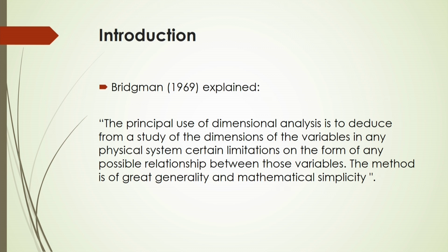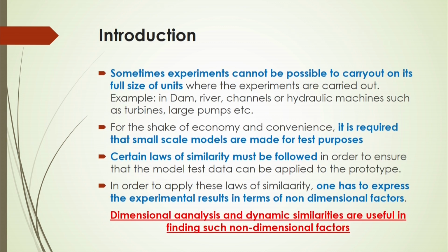So, dimensional analysis is done to reduce the complex phenomena of the fluid flow operation to its simple form. Sometimes, when you do experiments, the experimental observations cannot be interpreted in such a way that you get the exact phenomena if you are considering it on a large scale. So, you have to do some experiments on a small scale, and scale those small scale phenomena up for the large scale system.